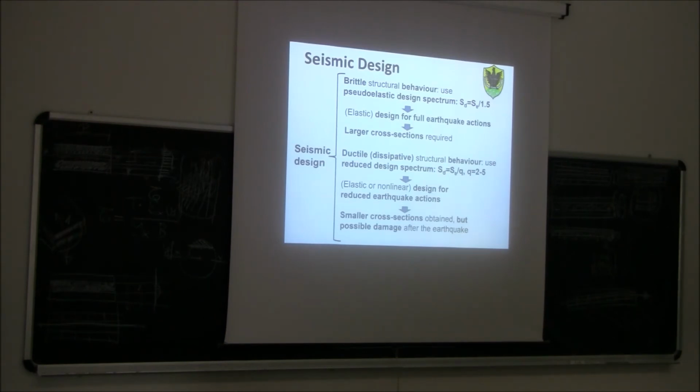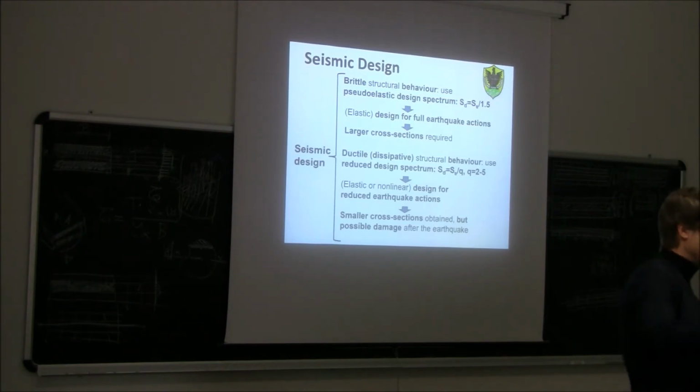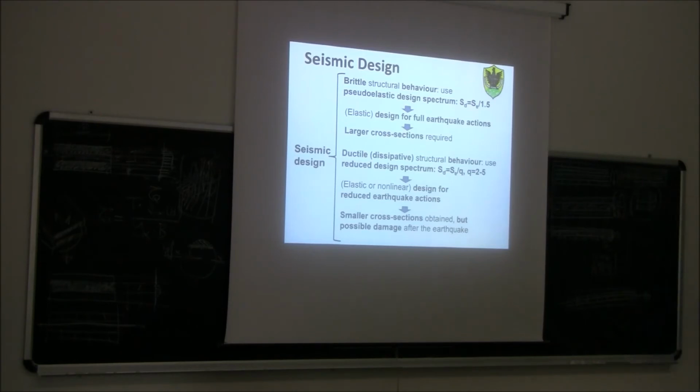Exactly, because before you said nodes, which is incorrect. If you want to be rigorous, it's not the node itself, it's actually the beam. It's not a cross section, it's the length of the beam, which is more or less 1.5 or 2 times the effective height of the beam, at the section with the beam and the column. So the plastic hinge is located on the beam, but very close to the column, to the node region. With capacity-based design, we need to make sure that this zone can dissipate energy.